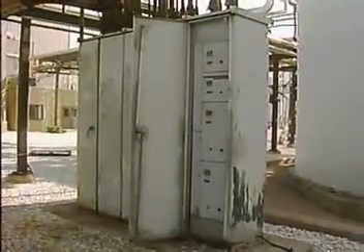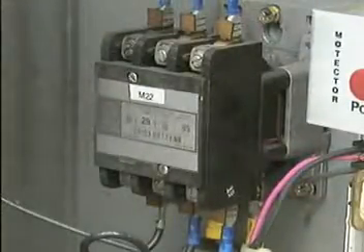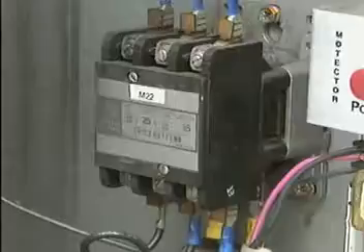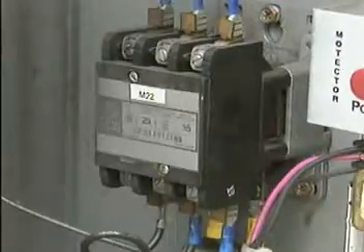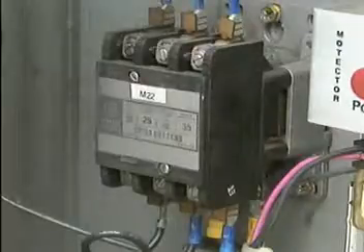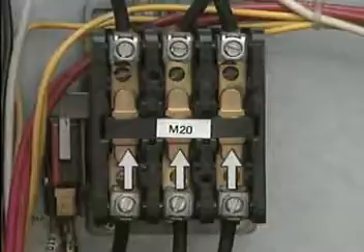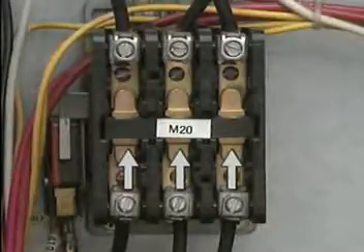One advantage of using a contactor in an AC motor controller is that it can be energized from a remote location using a voltage that is lower than the motor's operating voltage. The power circuit is energized or de-energized by devices operated by the lower voltage control circuit. This protects personnel from high voltage hazards when they start and stop high voltage motors. An AC motor controller typically has 3 sets of contacts, one set for each of the 3 phases of power in the AC power circuit.